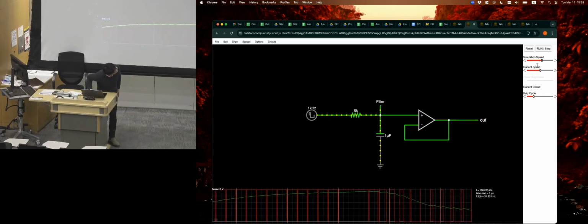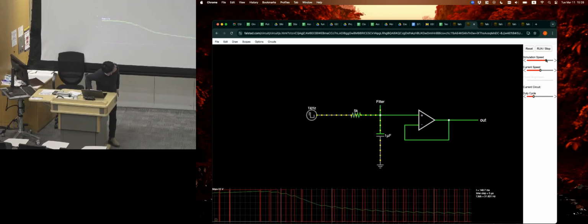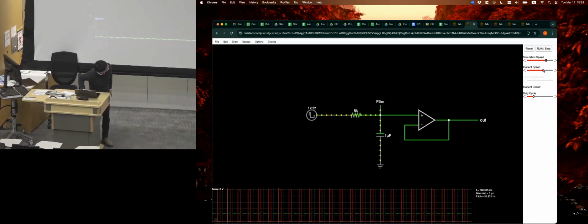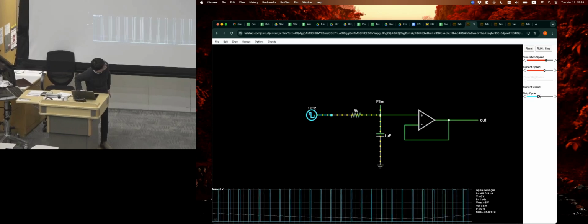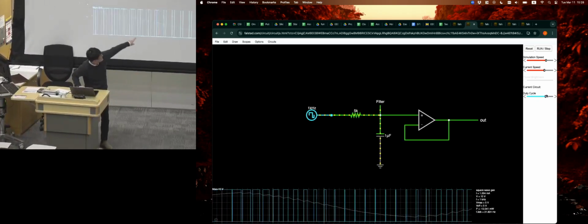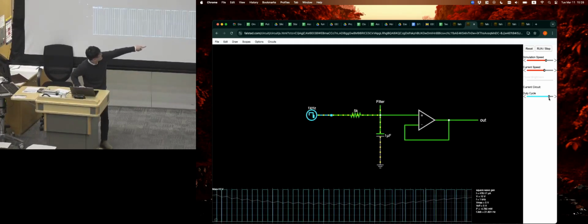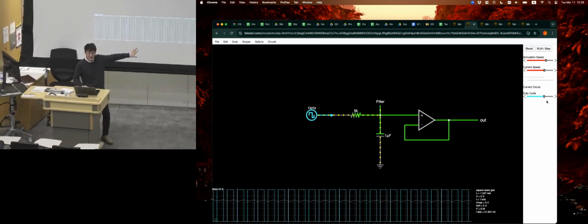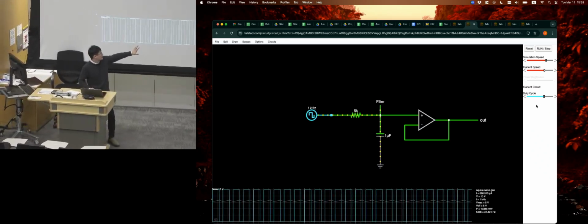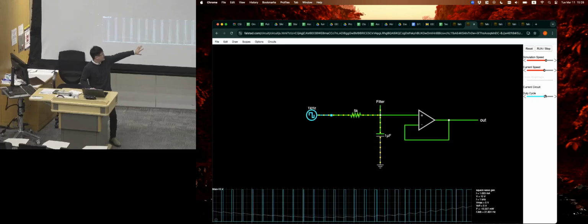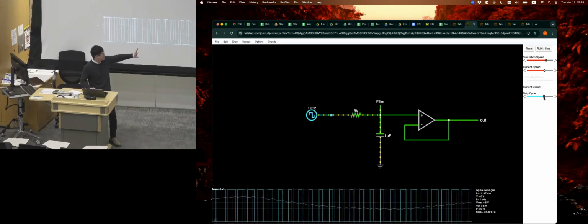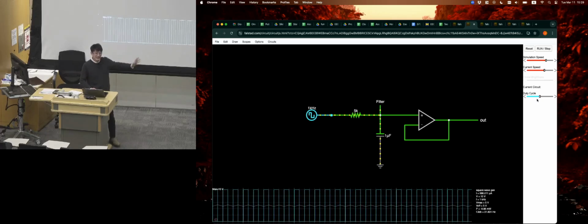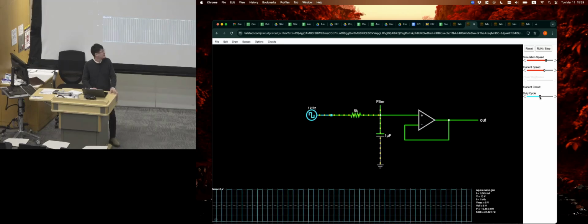Let's see if I can make the simulation much faster, and also the curve speed faster, so that hopefully we can see something more smooth. Were you able to see that? So basically, it's some form of sine wave analog signal outputted from the system. Although you will see at each stage there is a little distortion caused by the RC circuit, if you do it cleverly and gradually, then you have a pretty decent analog output.